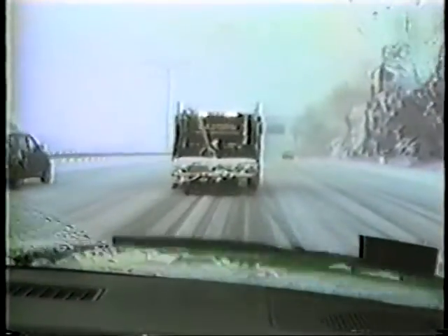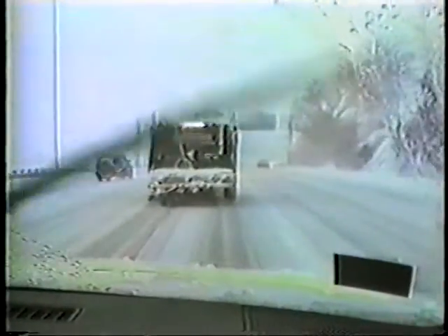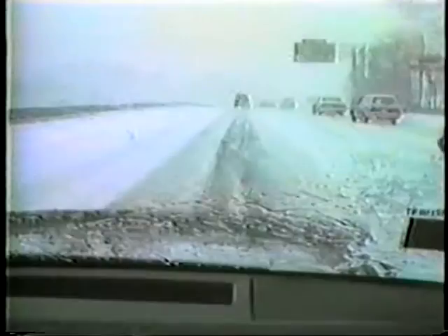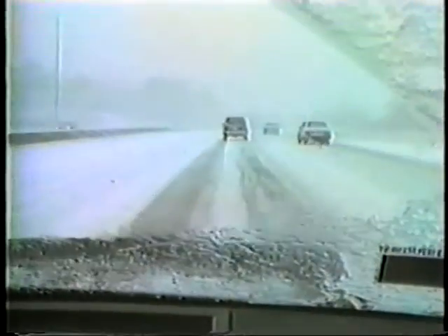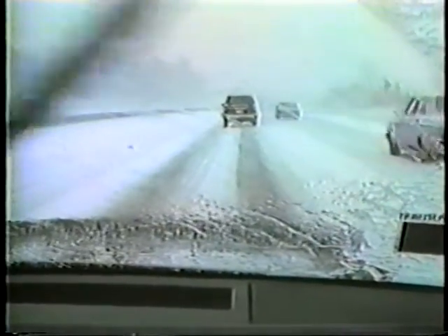They also can be applied on wet or thin snow or thin ice-covered pavement. On snow, they must be applied before a pack develops. Until the thin ice is melted, a liquid will create a very slippery condition. Therefore, a liquid should not be applied to ice during critical traffic periods.